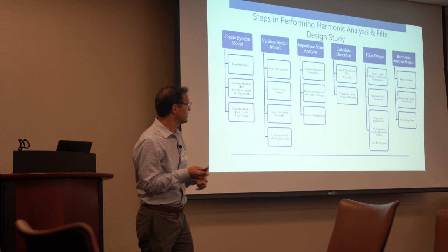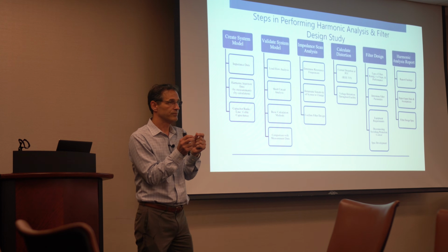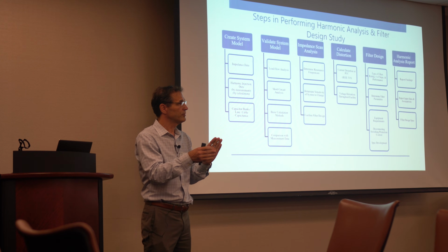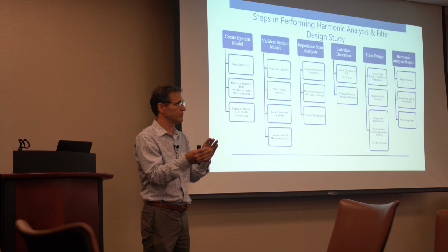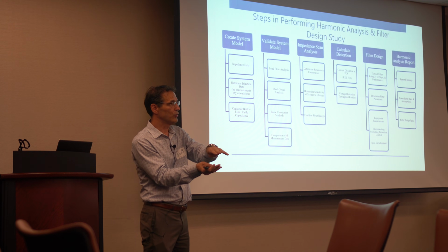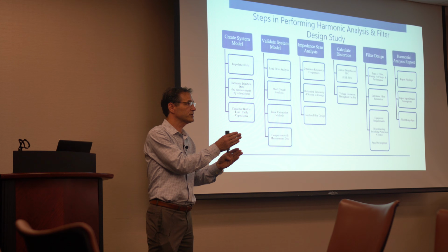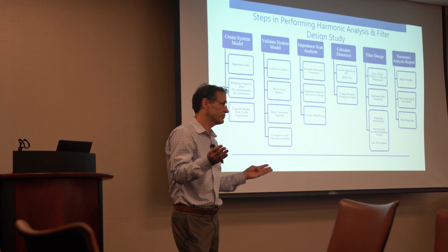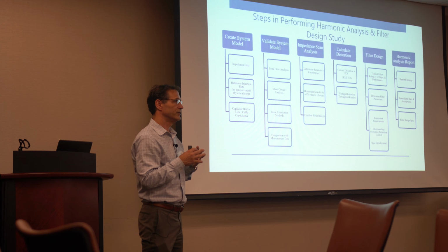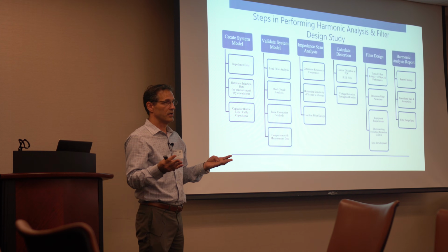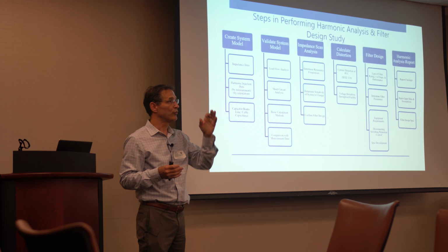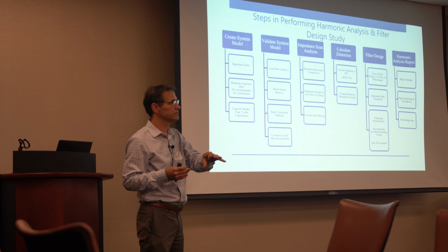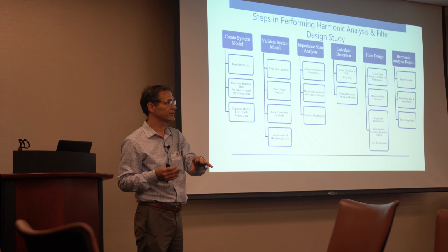So some programs allow you to add up all the harmonic current in the network, and you can do it in Excel, come up with a total, and make that your current injection on the bus bars. You just sum it all up as one equivalent. That's the simplest way. It's the way I like to do it. I just add everything up. I do some kind of load study and say, okay, where are my large VFD drives? Add all those up. Based upon the signatures, I have a total.